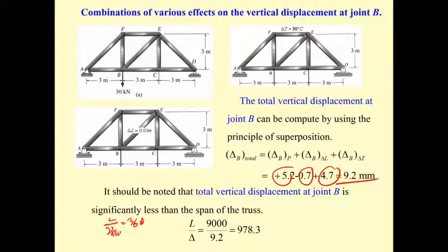Okay, that's if there is no wall under the beam. But for the truss, usually we set the allowable deflection very large because the span of the truss is usually very long. So when they design the truss, you must control the deflection of the truss as small as possible. Okay, usually it's not 360.